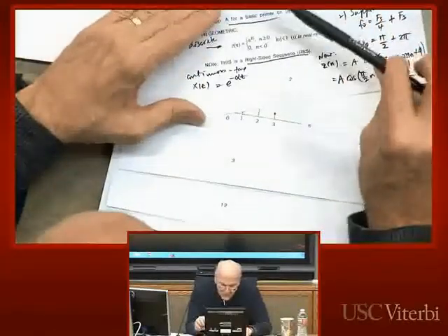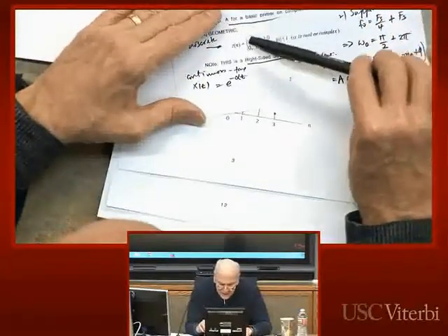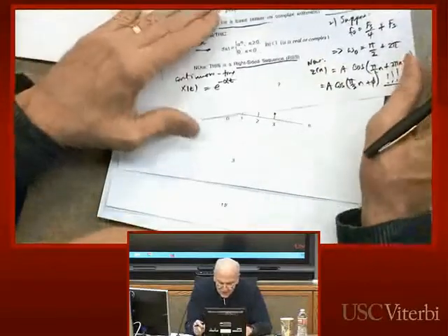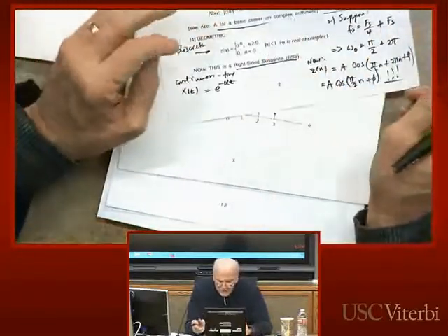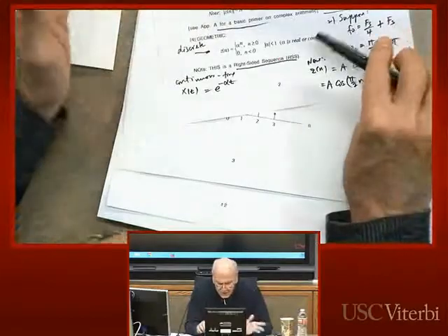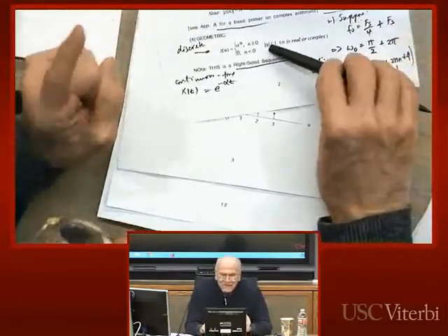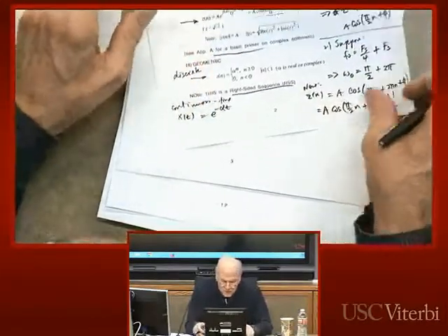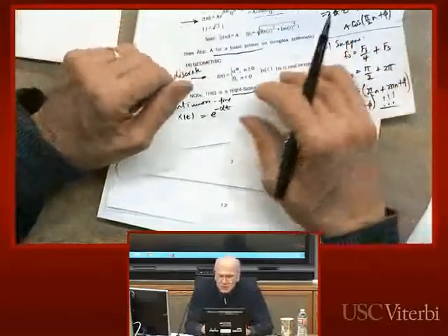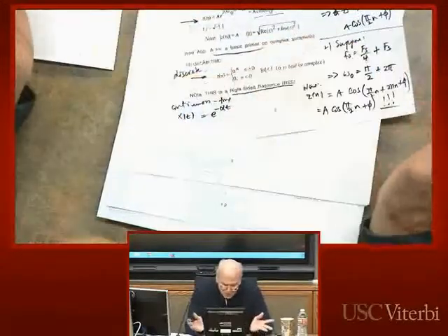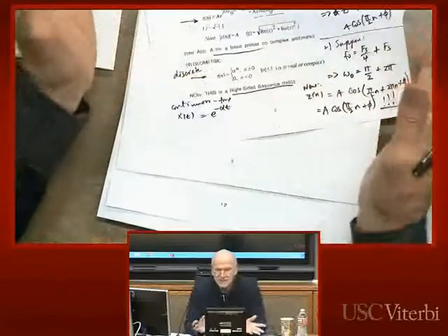It's a little bit different, but it's alpha to the n for n greater than or equal to 0. Typically, the magnitude of alpha is less than 1, but it could be real or complex, and it doesn't have to be less than 1. When we talk about the Z transforms, we will permit signals that actually blow up. You haven't seen those before in continuous time, but you will here.